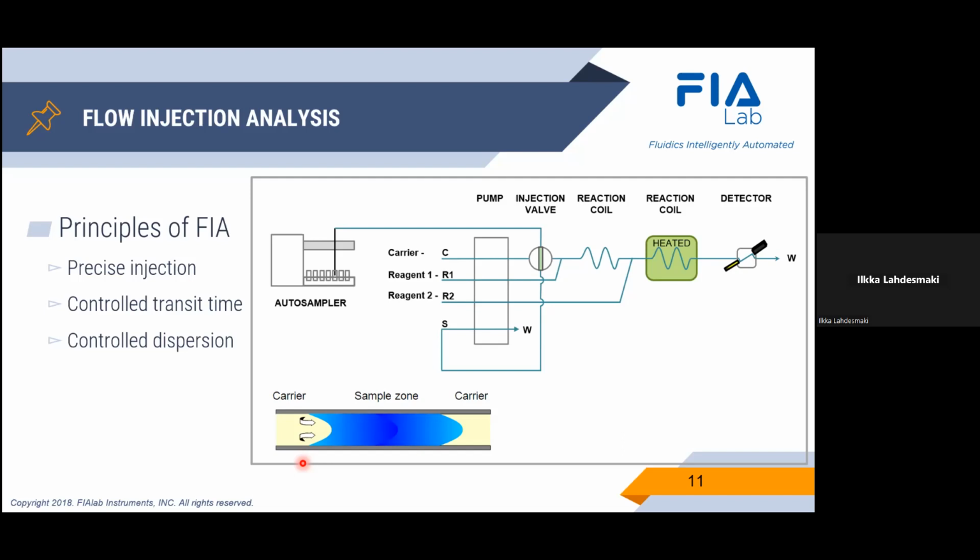So these are the three principles that need to be sound and fulfilled in order for the FIA instrument to work well: precise injection volume, steady transit time, and controlled dispersion or dilution.